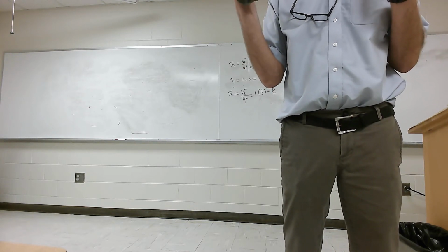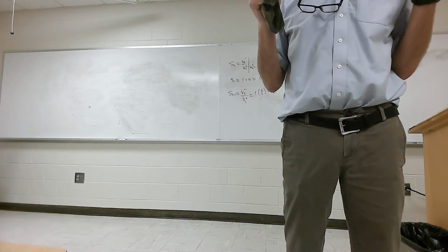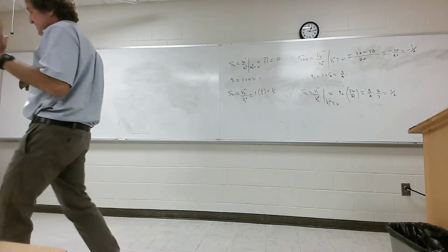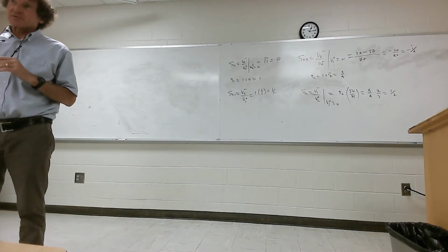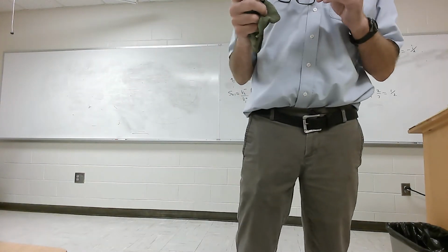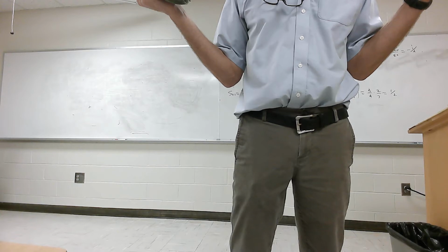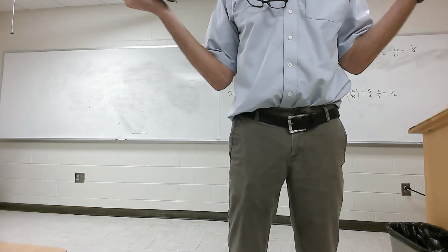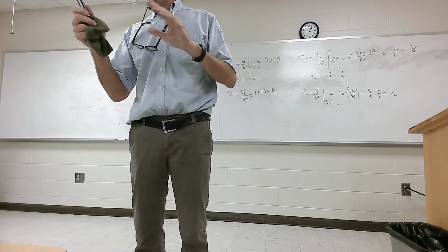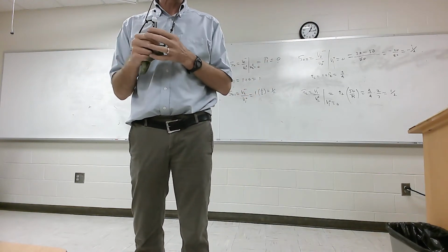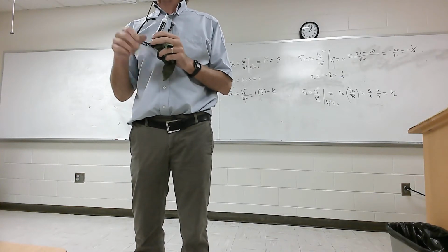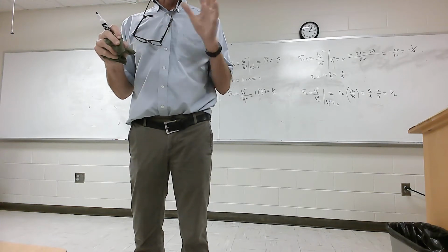You don't need to do any of these S parameter things. You're going to see it's S transpose times S conjugate. If they're multiplied together and it equals the unitary matrix, which I'll show you, it's just ones on the diagonal and zeros everywhere else, it's considered lossless, but just look at it. So there are no resistors, there's no problem. Now, if you're doing tests and you get a whole bunch of S parameters, then you have to do the other thing to see if it is lossless. Generally speaking, there are no absolutely lossless networks, but there are a lot that are very close. So just remember that in the real world.